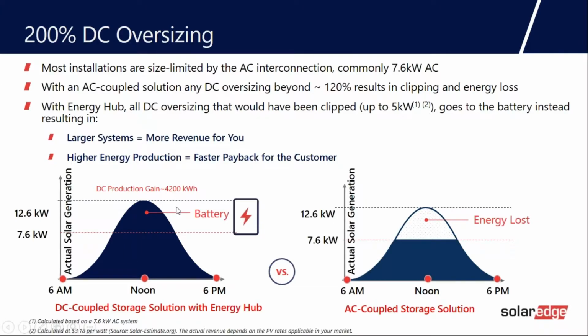So this is the biggest reason why I like DC coupled, because as a solar installer, I make most of my money on the roof, right? So if I can go with a higher DC to AC ratio, I can install more solar panels on a roof. That system will work much better during a grid outage during the day, even if it's low light, there's snow all over. Well, if there's snow all over the panels, there's not a whole lot we can do. But there's snow everywhere, hopefully not on the panels. You can still really charge your battery and power your home with the high DC-to-AC ratio.